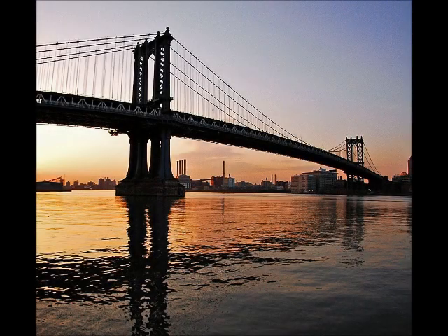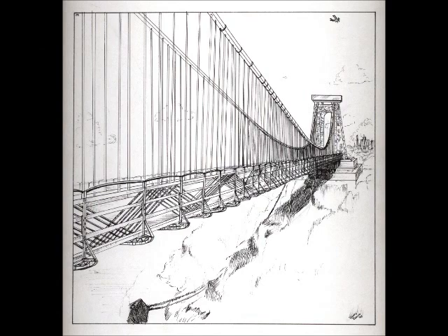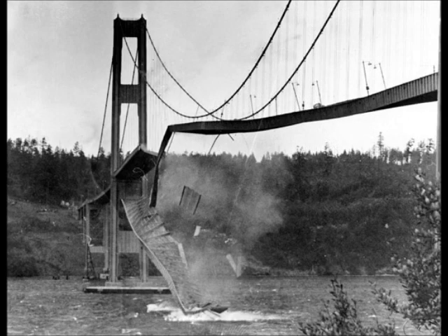The suspension bridge. A suspension bridge is one where the road deck is suspended from cables that are strung across the river, or wherever the obstacle happens to be. There is no support in the center of the span, and the deck hangs below the supports rather than resting up and down. One example is the Tacoma Narrows Bridge, that unfortunately displayed rather too much grace and flexibility, becoming known as galloping girder, from the wave-like motion of its deck even